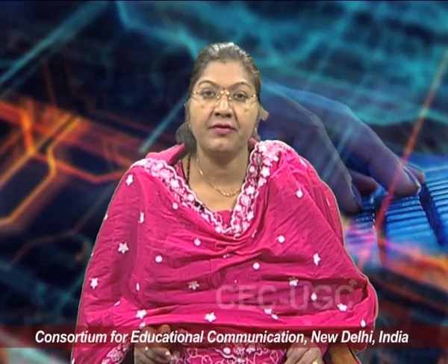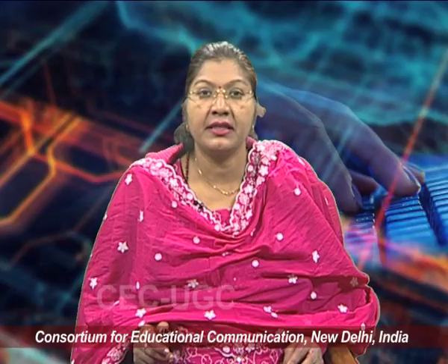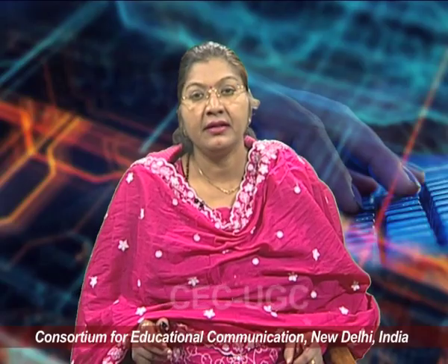Another type of heater is the fan heater. The fan heater operates using resistive or ohmic heating, which is known as the Joule heating effect, in which process electric current flows through a resistance material, converting electrical energy into heat. This heat is produced on the microscale as conduction. Electrons transfer energy to the conductor atoms through collisions. A fan then disperses the generated heat into the surrounding environment.